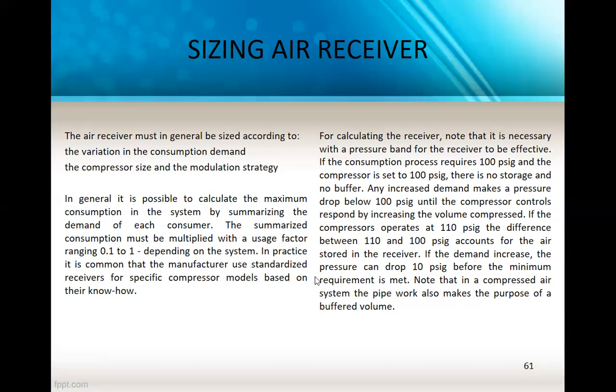Same, no receiver, but the compressor is running. If the demand increases, the pressure can drop 10 psi gauge before the minimum requirement is met. Note that in a compressed air system, the pipe volume also serves the purpose of buffer volume.